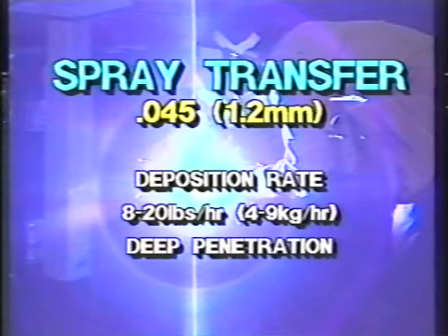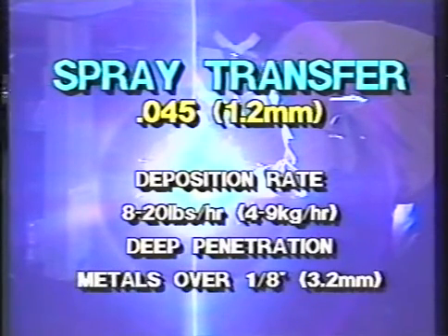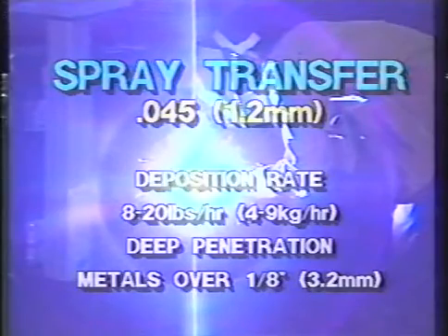With spray transfer, the penetration is excellent. The application range for spray transfer is 1/8 to almost any thickness. But remember, when utilizing spray transfer, it's a hot process. The radiation is high. You need good protection for not only the hands, but for the neck and for the body. And ensure you use a correct lens for spray transfer.